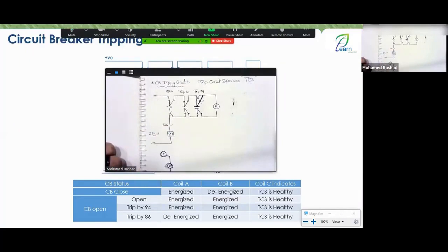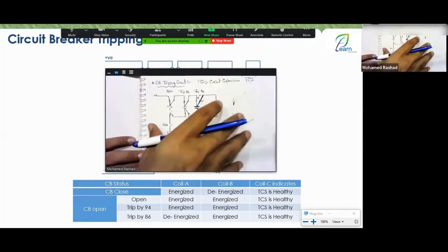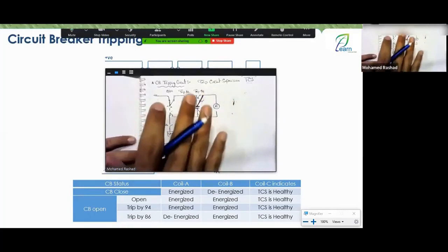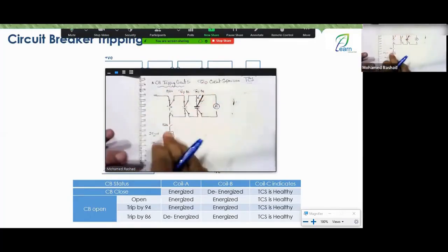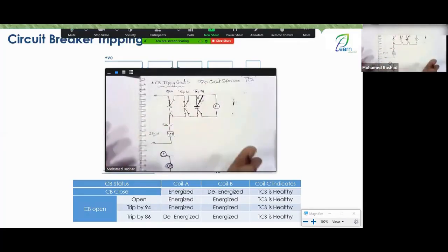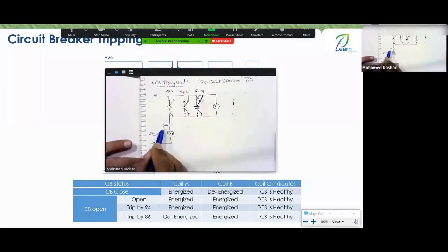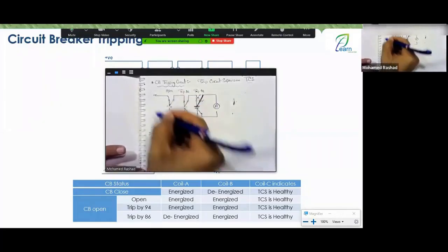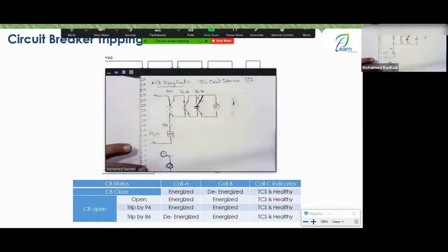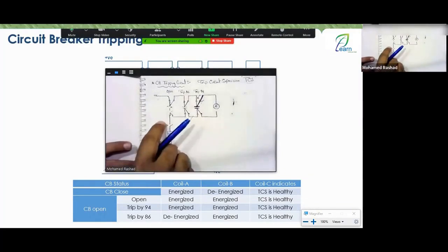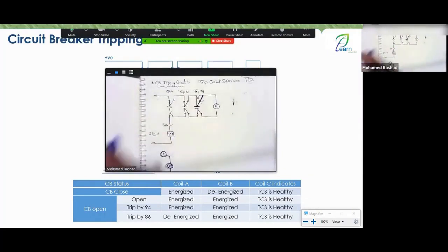Okay, Rashad, in the interlock in the closing circuit, I used to use 52B, right or wrong? Here, why 52A? Let's go back. The drawing standard says the breaker is drawn with all its contacts in the state that the breaker is open, right? So if the breaker is open, I need this contact to be open. Why? So that DC doesn't reach here again. Unlike the closing circuit, where the contact is closed because the breaker is open, so it is prepared to receive a close command.